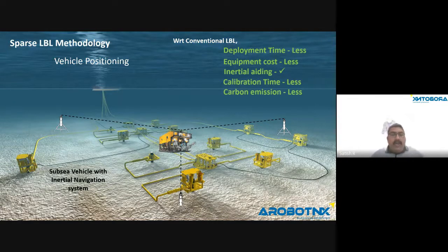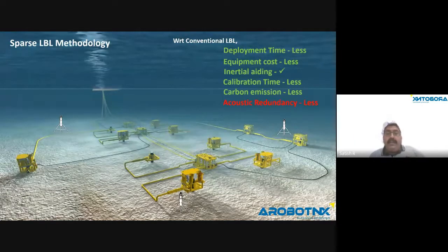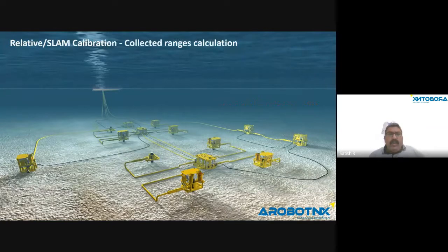So it is able to talk in line of sight, and also with a perfect geometry you could talk with the transponders and get your localization powerful. If you find some INS issues there, you can definitely go somewhere in between 2 transponders and get your position updated, carry out a small error calculation and come back and carry out your operation. That also is possible. So the accuracy redundancy is less. You just need only 3. So that is something we have done.